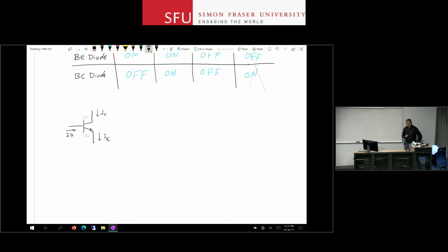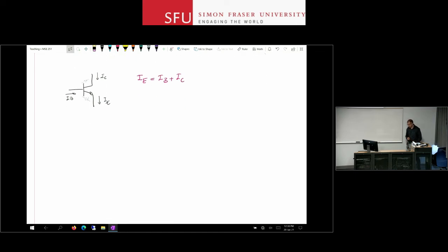So I remember that I have a diode between base and emitter, as shown on that graph, common base, and then 2 N regions. One is used at the collector terminal, one at the emitter terminal. So we saw that KCL imposes this on us: IE is IB plus IC, for the direction of currents shown in this circuit.